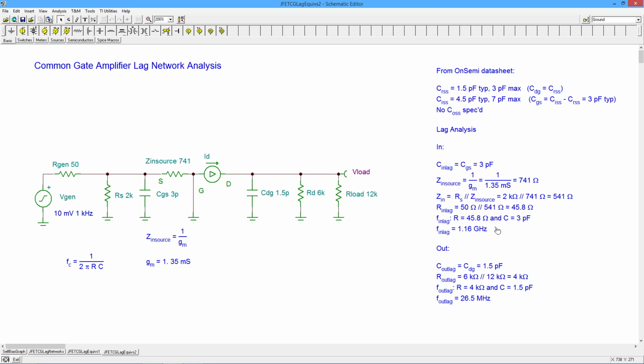Guess what? That's not real. When you have really small resistance values and really tiny capacitors, you can end up with calculated values that are actually well beyond the capability of the FET. Remember, we're dealing with a FET model here. So do I really think this FET could go out to 1.1 gigahertz? No, I don't. Not for this little 5458, I don't. But nonetheless, as you're going to see, this is not a problem because we now move on to the output